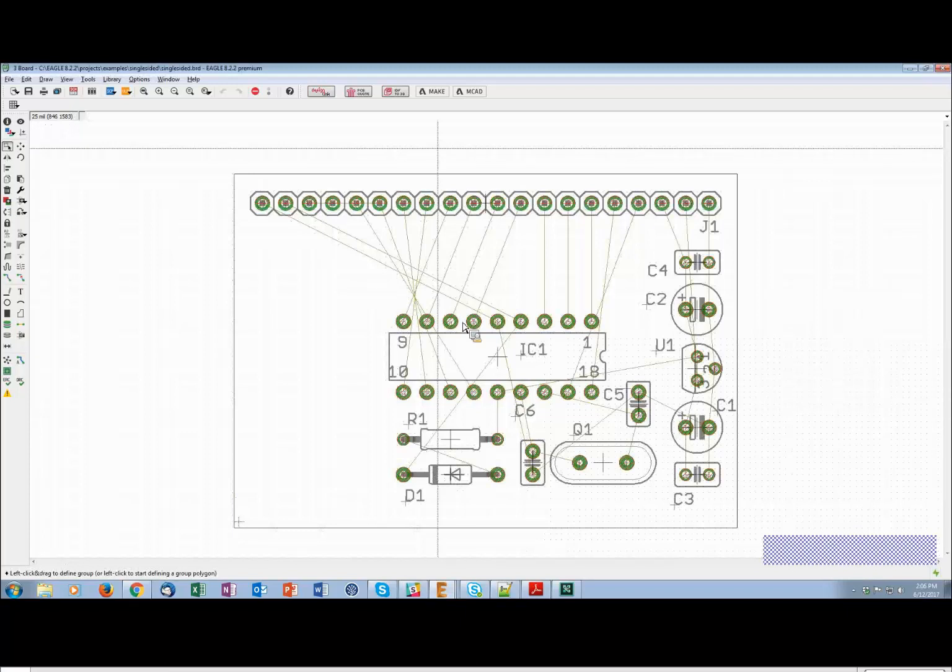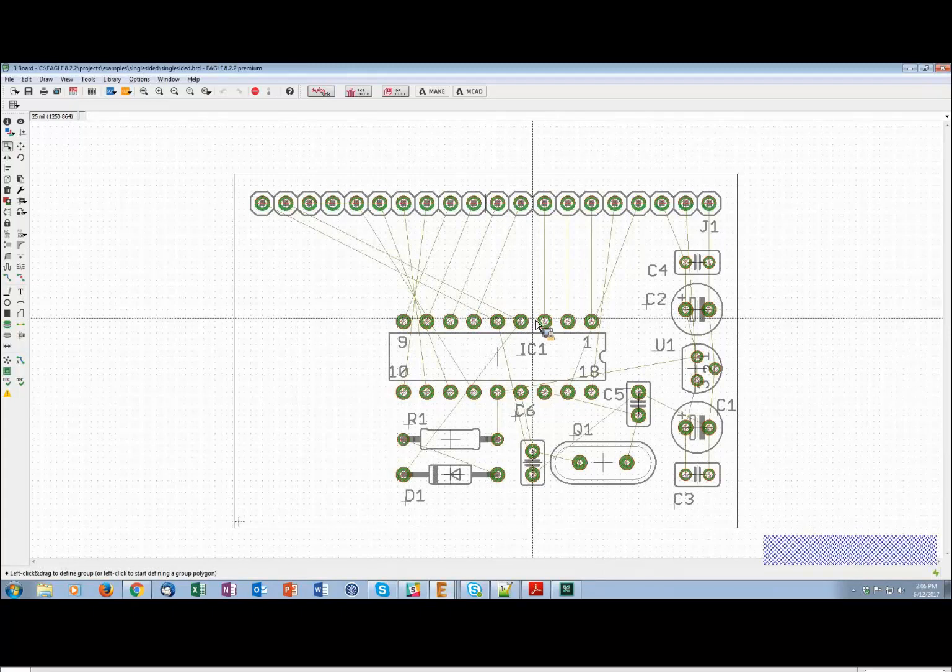You may have a restrict error going on, maybe a clearance where the Autorouter can't get in between pads to route. As a rule, the Autorouter will not route something if doing so will generate an error. So if you're using the Autorouter and you see a certain area of your board that never gets traces, or doesn't seem to be touched much, it's a good idea to run the DRC and make sure there aren't any violations there, because if there are, the Autorouter won't be touching them. Of special interest are overlap, clearance, and restrict errors like we're seeing here.